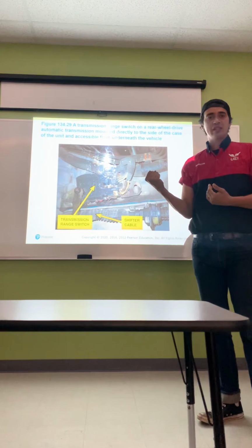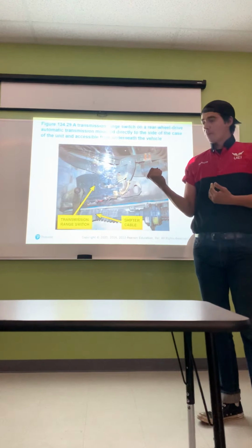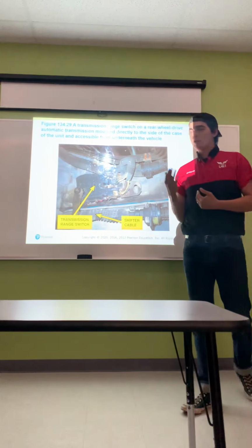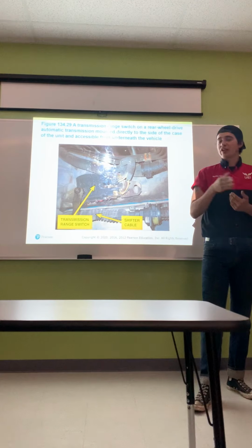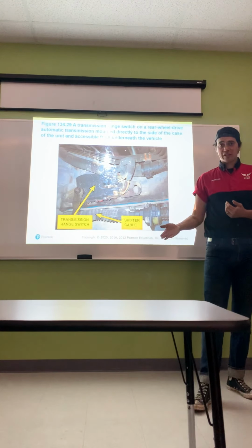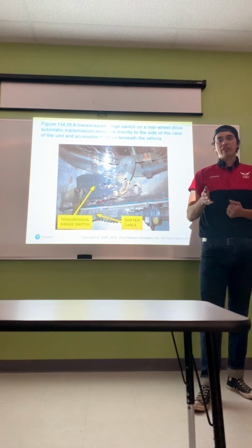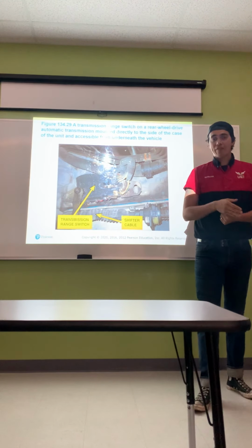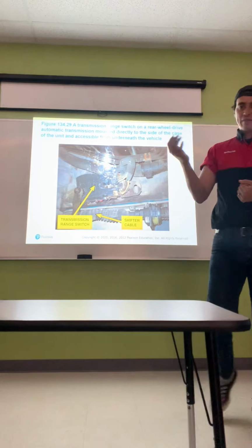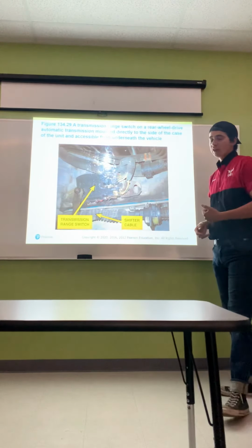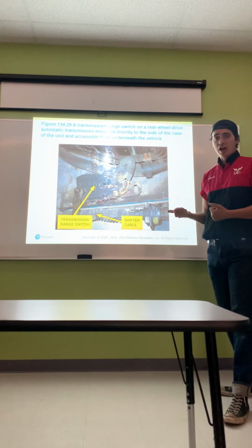It's not going to upshift into the next gear or the next gear. But let's say you keep it in third. When you keep it in third, it's only going to allow you to shift up to third. You're not going to start off in third gear. You're going to start off in first gear. It'll shift in second, it'll shift in third, but it's not going to shift into any other gear after that. Then when you shift into drive, it'll go into fourth gear, and then obviously it'll go into overdrive if you have the overdrive switch on.